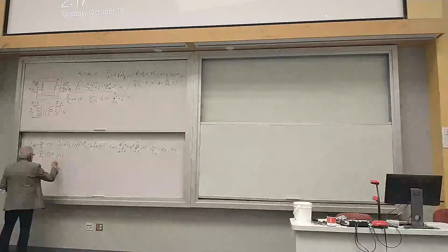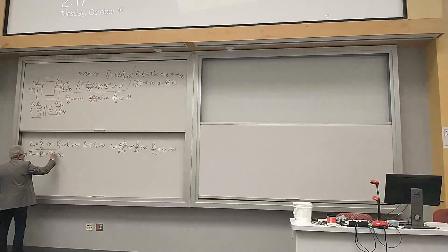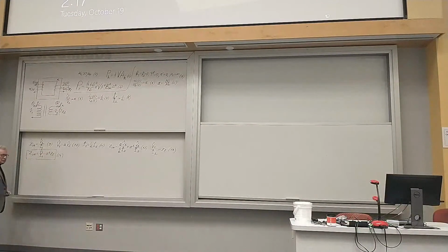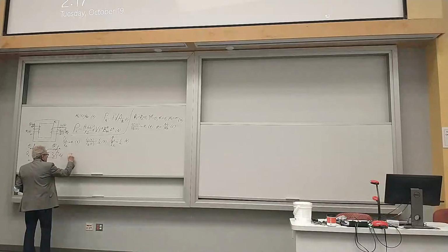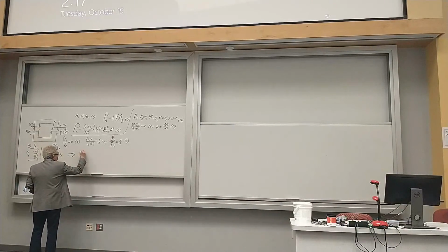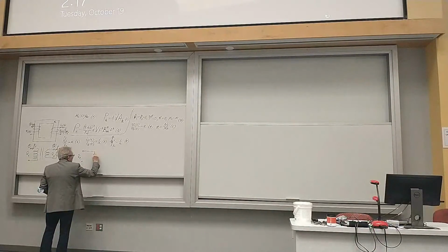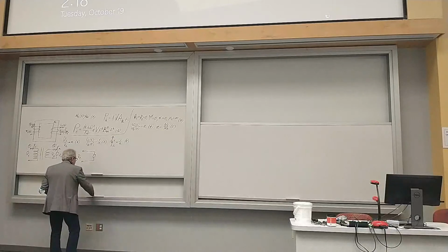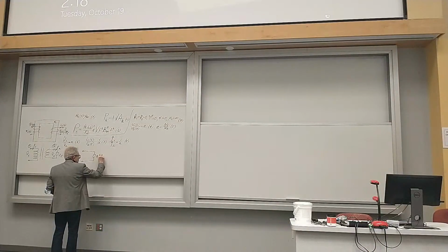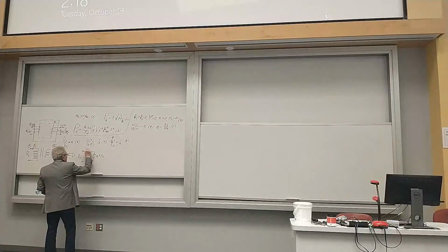Very interesting consequences can be found from this very important formula. The first consequence is the equivalent circuit of the transformer, the ideal transformer. So I can claim now that the equivalent circuit of this ideal transformer can be represented as follows: here will be the primary voltage, here will be the load, which is equal to A squared times load impedance, and this will be the primary current.